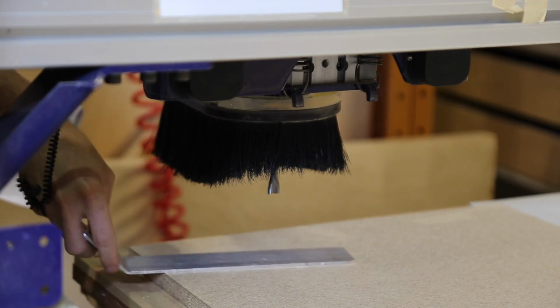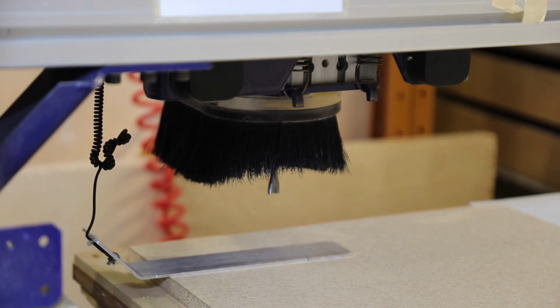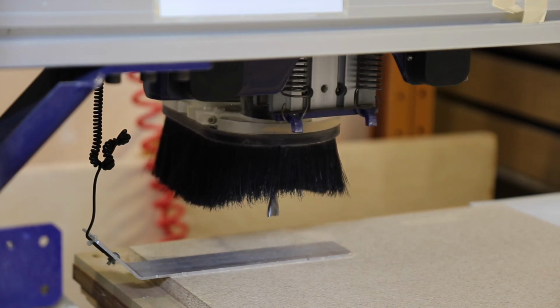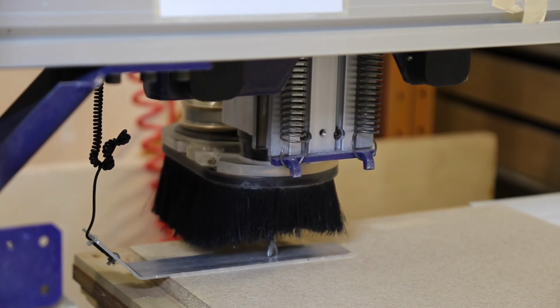Unfortunately, this will also reset all of your zero coordinates, which will need to be re-zeroed before continuing to cut your file. Neglecting to reset your zero coordinates is not an option, as the bit may drive down into the spoil board, ruining both the bit, the work, and potentially the collet.